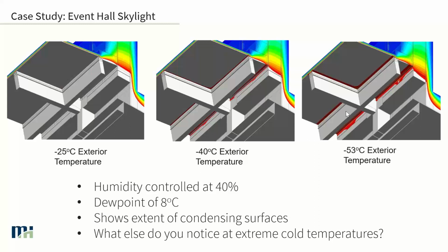And so you can see, the system performs pretty well. There's maybe a tiny piece of condensation potential here at lower temperatures, but that will probably be picked up by the condensate track that usually runs along these skylights. So under normal conditions, that may be so small that you're potentially not going to get condensation there anyway.